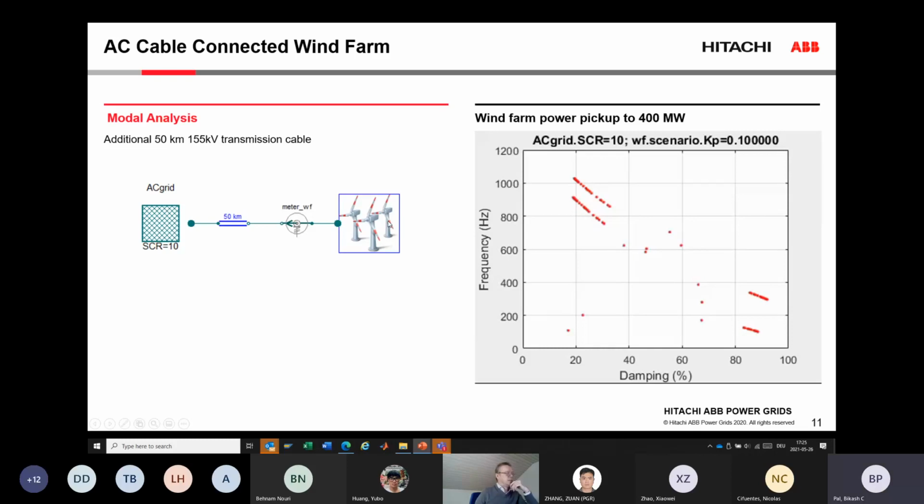No, I think the problem was different. I can send you some report. It is because there are long AC high voltage cables. They had the STATCOM in between, and that STATCOM control loop was somehow wrongly tuned with the wind farm.